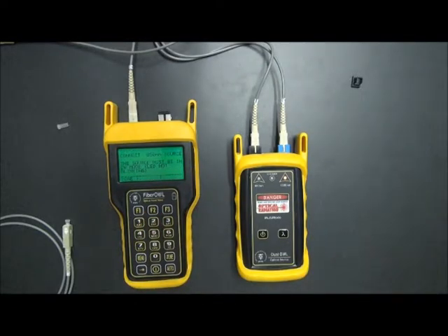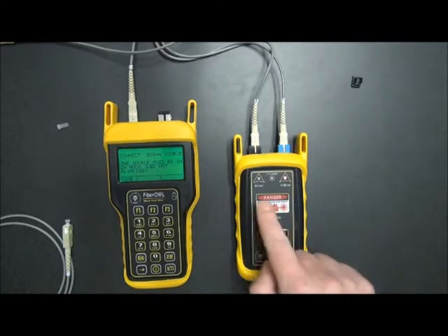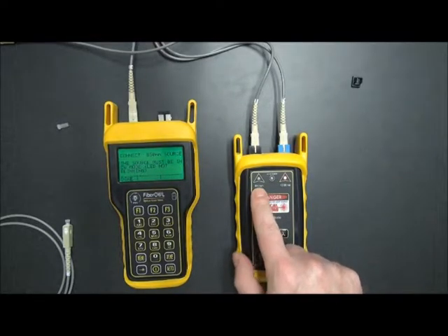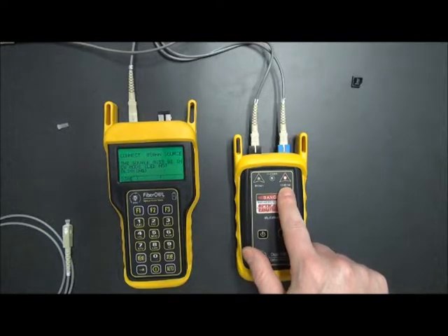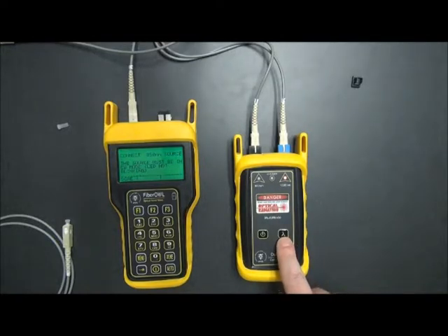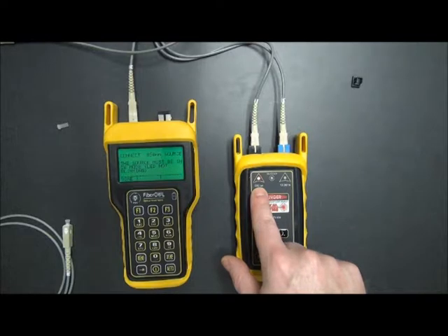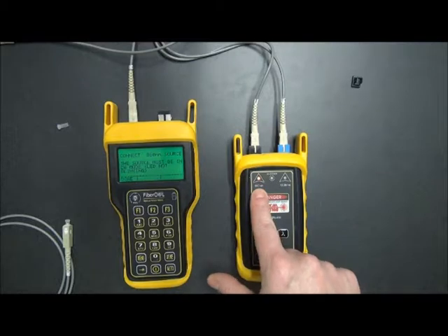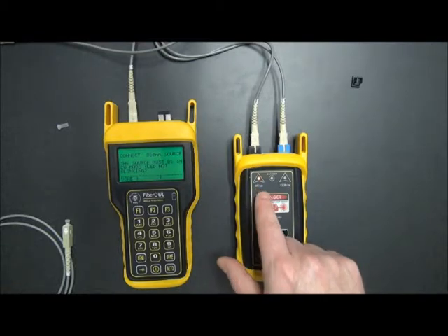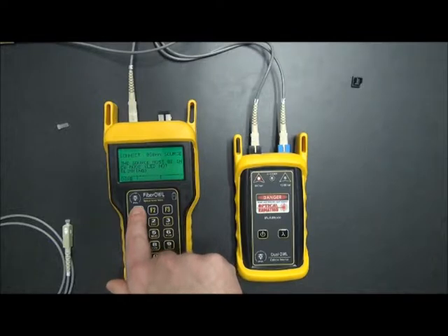And we have a screen here that says connect 850 nanometer source. The source must be in continuous wave or CW mode. An LED must not be blinking. The LED it's referring to here is the indicator LED. Now, you might not be able to see it real well, but the 1300 wavelength is actually selected right now. So we have to switch the wavelength with the lambda key. When you're switching wavelength with the dual OWL, you'll notice that the indicator LED does flash briefly, but then it goes solid again, goes continuous. We have to wait till it's continuous before we continue here. So now that it is continuous, we can press F1 for done.